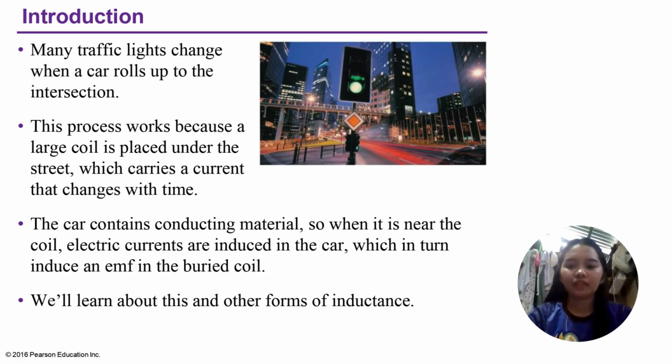Inductance is not merely a theoretical concept, it is a principle at work in numerous everyday applications. Consider traffic lights, for instance. The detection of a vehicle at an intersection often relies on a large coil buried under the road. This coil carries a current that changes when a car approaches, due to the car's conductive materials.